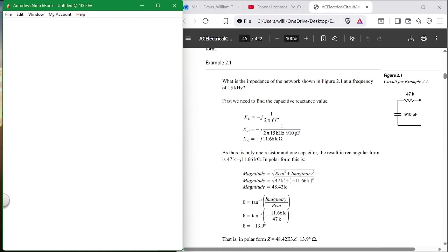Okay. So here I have a resistor and a capacitor, and I also have a frequency. Okay. So now X sub C is equal to minus j over 2 pi f C. X sub L is j 2 pi f L. You tuck those away, write them on your shoe, put them on your piece of paper, as you have to remember these, and then you go forward, okay? Please use these as something that you do not forget.